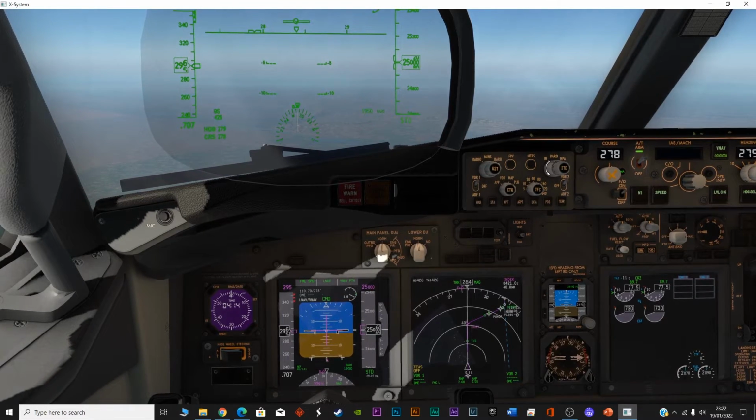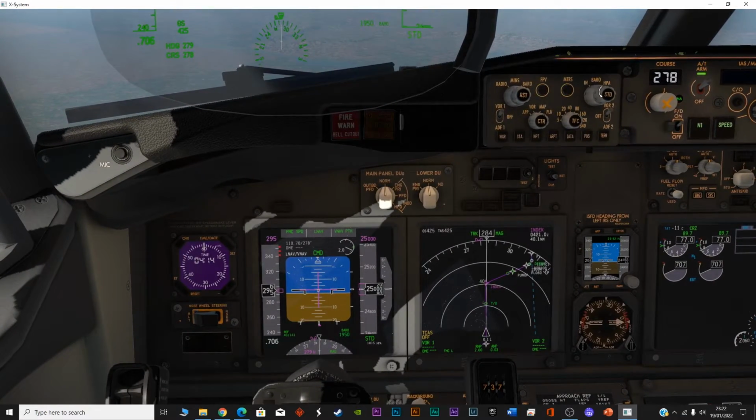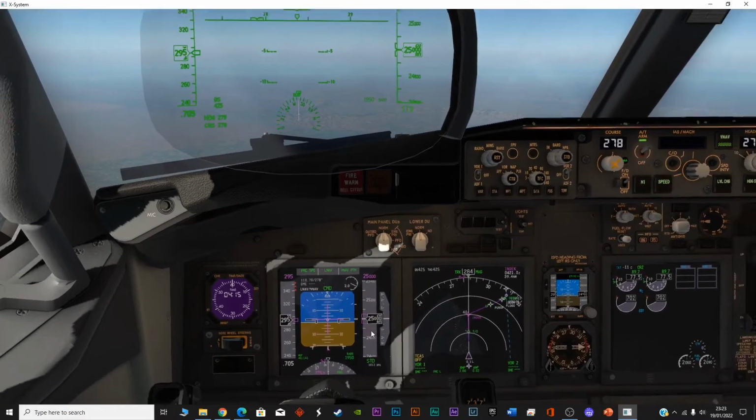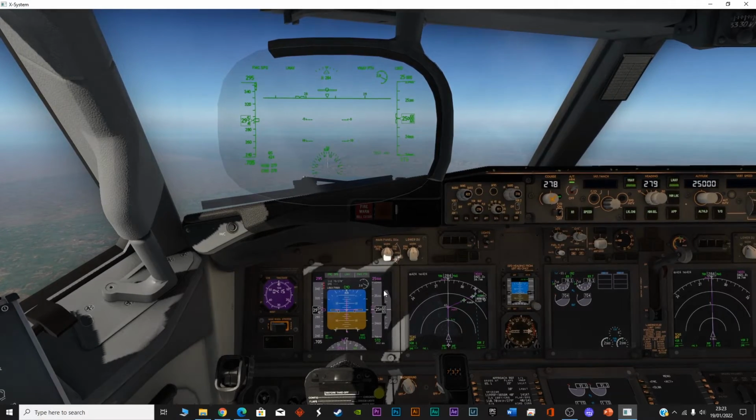So first of all, 1013, I will switch the units to HPA instead of IN, and 1013. Now I will use this line. Now you can see this information is here, but right now it is at standard. For every airport there is a transition altitude. For Islamabad International Airport it's 15,000 feet. How do I know this information? It's there in the airport charts.